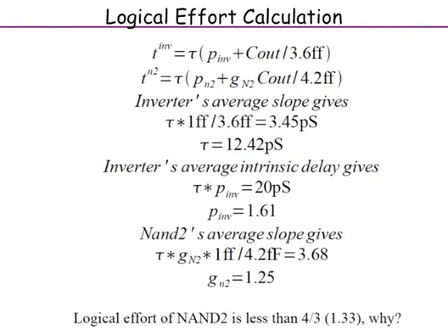And when that is 2 and PMOS is also 2, the input capacitance looking into that input of the NAND 2 is 4 units, 2 from the PMOS, 2 from the NMOS. For an inverter, the input capacitance is 3, 1 from the NMOS, 2 from the PMOS. So just by sizing and hand calculation, you would expect the logical effort to be 4 by 3, right? So that is what you would expect, 1.33.